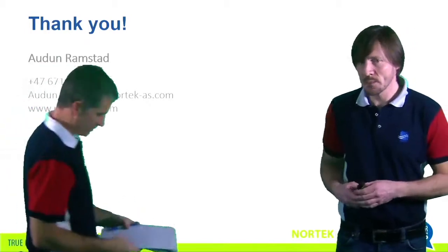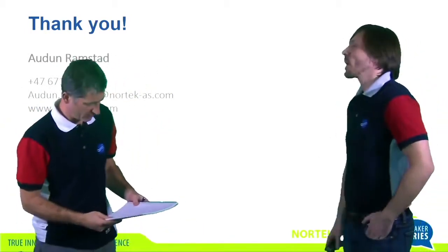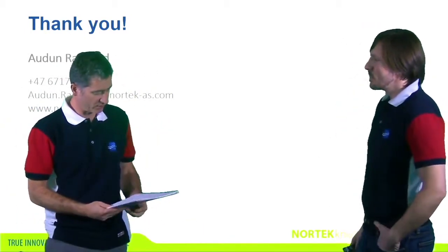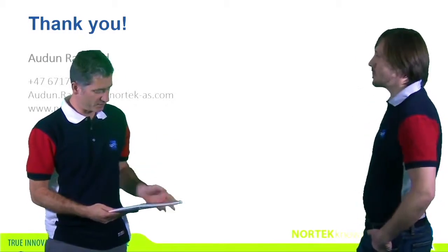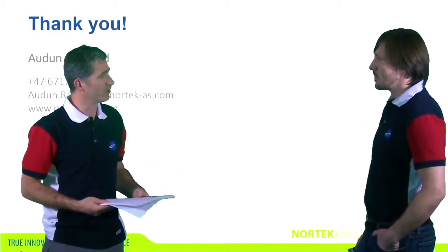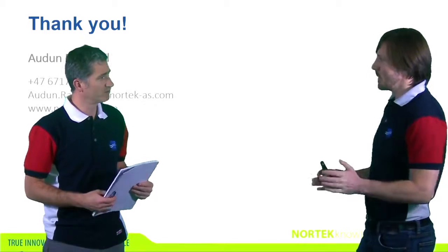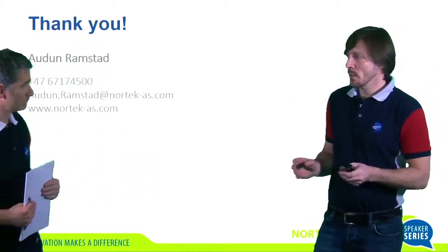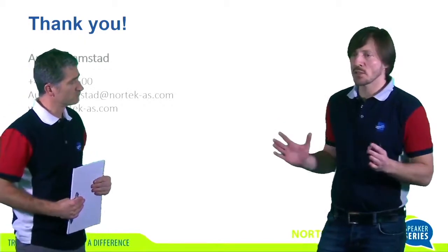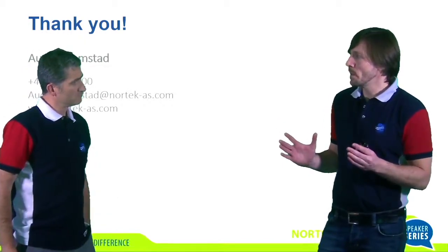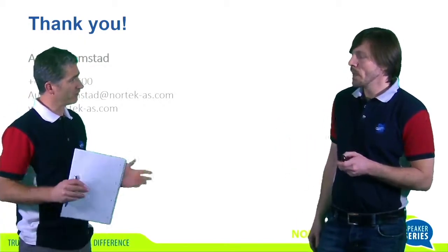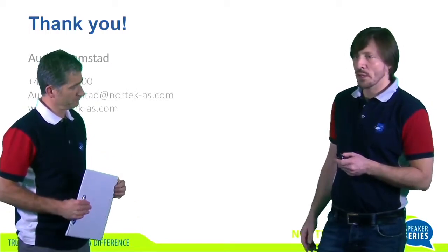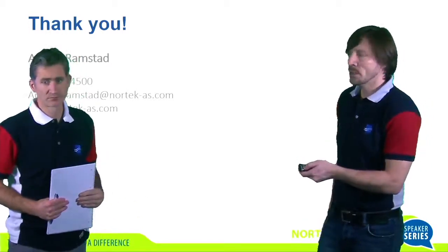Yeah, there was, in fact, one question that popped up during this. This comes from Hamish Kerr, and that is, is the chirp a fixed time period, or is this something that can be altered? Oh, the chirp time period, yes. That's by changing the velocity range. You change the time period of the chirp. Okay, so it's an indirect change. Yeah, it's inversely proportional. Maybe we can go back a little bit and see the expression.